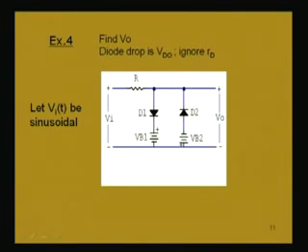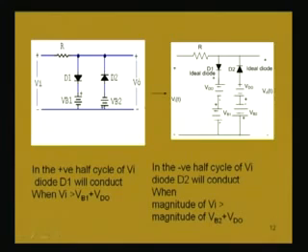So, now, as it is easier to deal with such circuits if we replace the diode by its constant voltage drop model, we will be doing that. So, this circuit we are drawing again by replacing the actual diode by its constant voltage drop model, that is shown here. So, this is diode D1 and this is diode D2. Both these diodes actually have the same drop Vd naught.